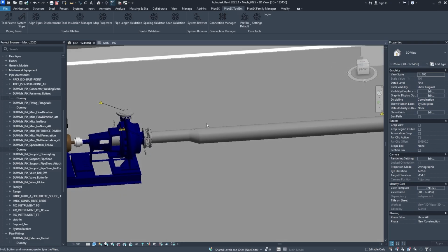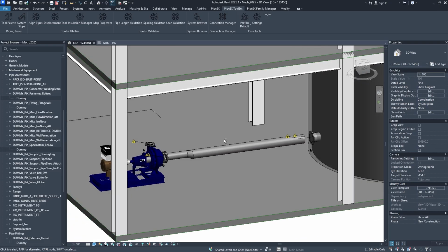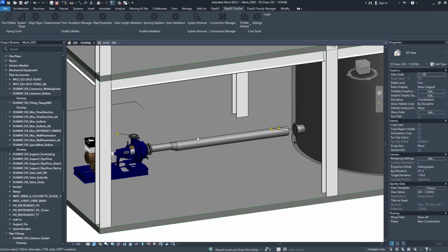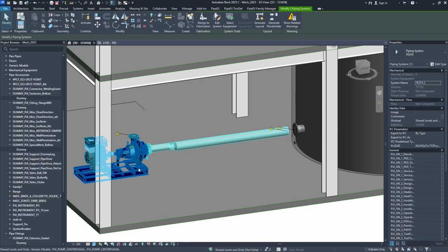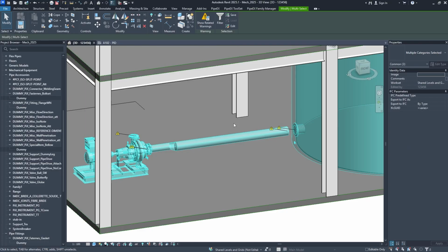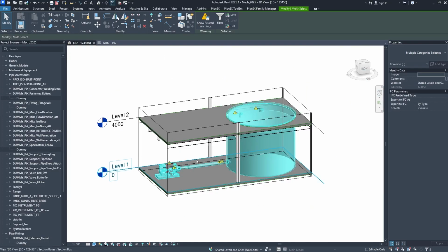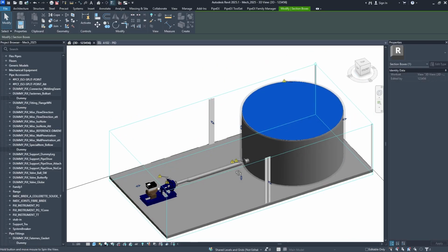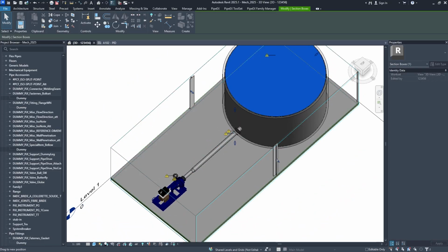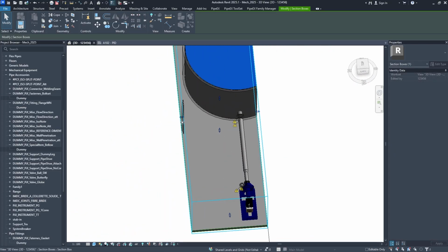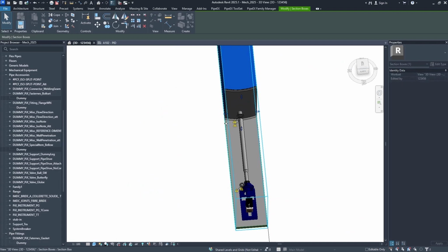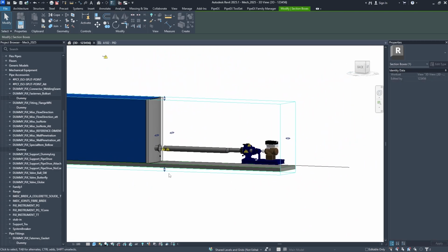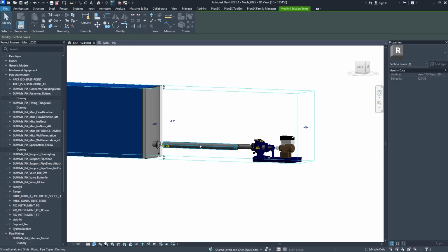What also will be better, just to limit the surroundings that you see around, we can isolate those components with the selection box. Just do not see all the components that we have around, at least when we're creating this model, because this one also will limit Revit from snapping to every single surface that we have around.